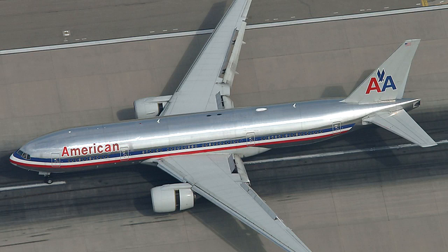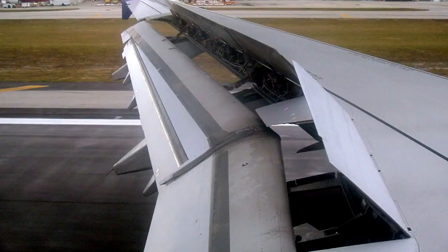In this lesson, we will discuss the aerodynamic devices that are used to reduce lift and/or to slow the aircraft down. A spoiler is a device intended to reduce lift in an aircraft. Spoilers are flat panels on the top surface of a wing, which can be extended upward into the airflow and spoil it. By doing so, the spoiler creates a carefully controlled stall over the portion of the wing behind it, greatly reducing the lift of that wing section.